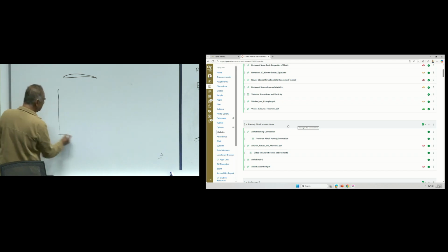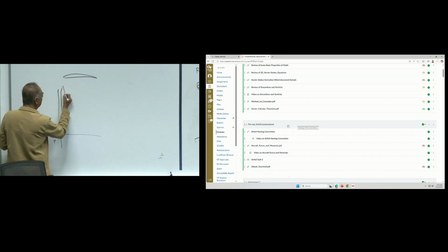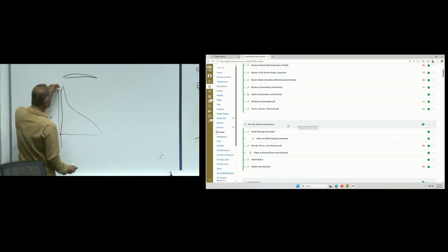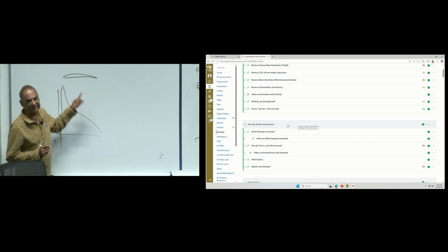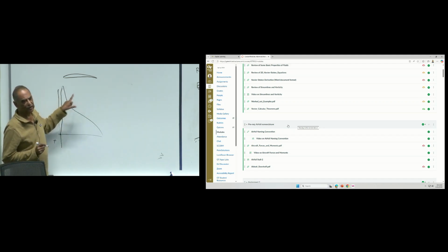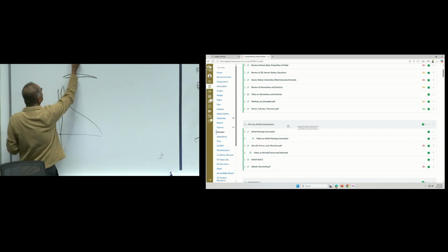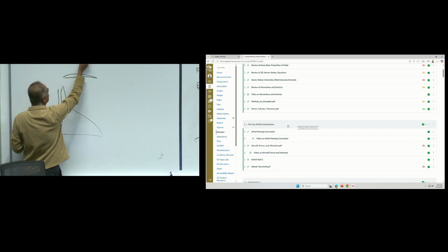So when that happens, the Cp value goes from positive to negative, way up here, and the pressure may start changing very steeply near the leading edge. This will usually be a low radius of curvature.